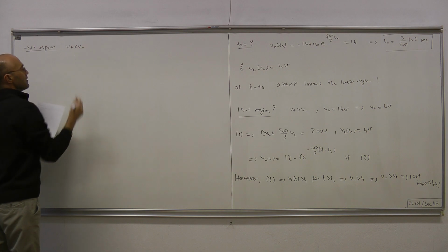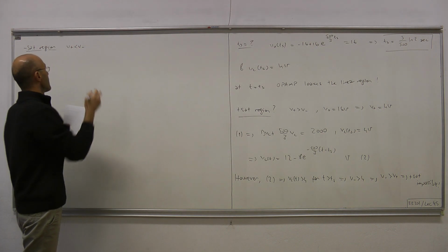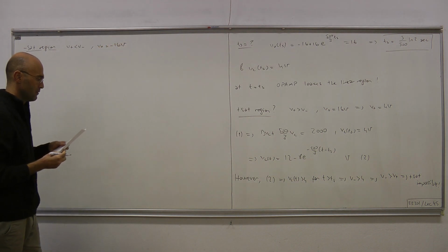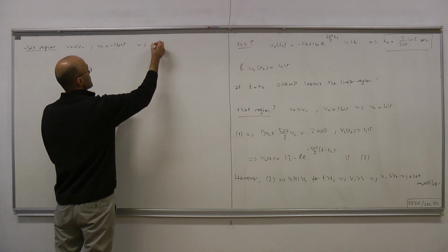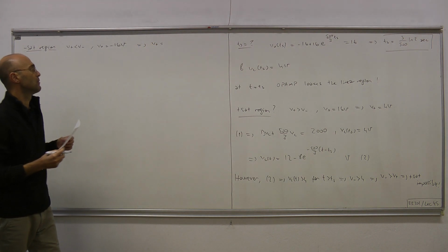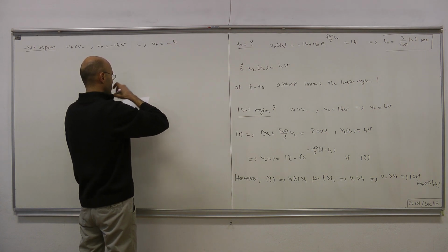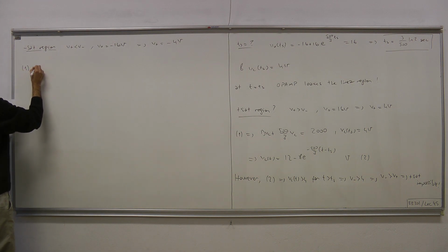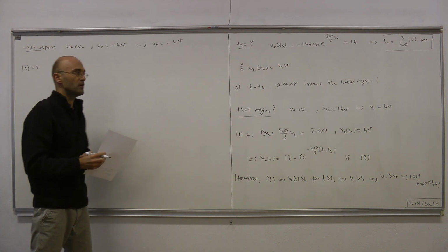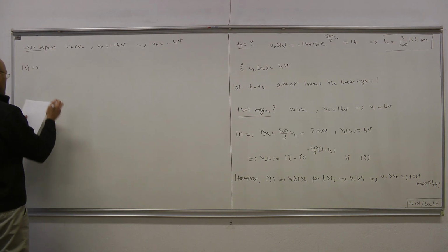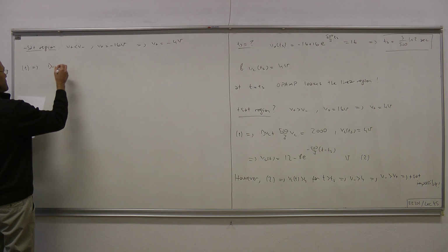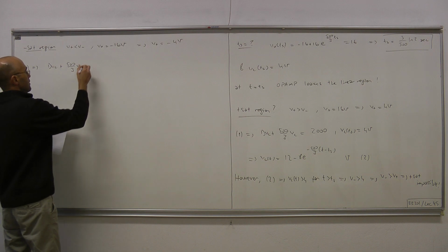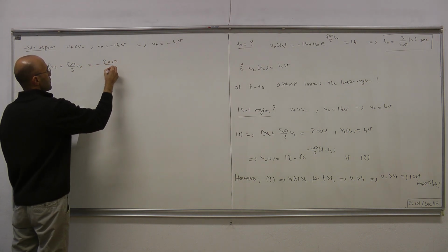Condition is that V plus is less than V minus, V out is fixed at minus 16 volts. That implies, due to the voltage divider, V plus equals 1/4 of that, minus 4 volts. Okay. Now, once again, using the equation that we obtained in the very beginning, equation 1, we have dVc/dt plus 500 over 3 VC, this time equals minus 2000 over 3.